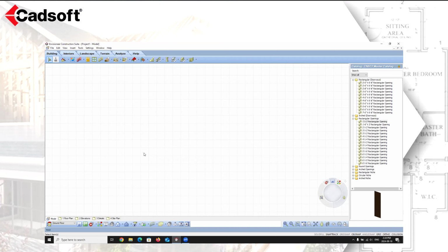So the first thing we're going to be looking at is drawing walls to exact dimensions. When you know the exact dimensions that you want your perimeter walls to have, you can use the Walls by Baseline tool. This option allows you to type in precise lengths for each wall. And as you draw your wall segments, a self-closing line diagram is going to be formed. When you have finished specifying your wall lengths, you are then prompted to specify an offset method for those walls relative to the baseline that you drew. You can offset them from the outer face of the veneer, the outer face of the wall core or stud, or from the inner face of the wall.